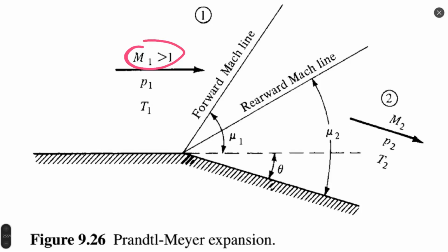Okay, I'm back. Supersonic flow must enter in contact with the geometry that is expanding area of the flow, and exit of this flow is also supersonic. When we compare this flow with shock waves, we see that flow is accelerating, and another big difference is that this flow is continuous and isentropic, where shock waves are not isentropic.